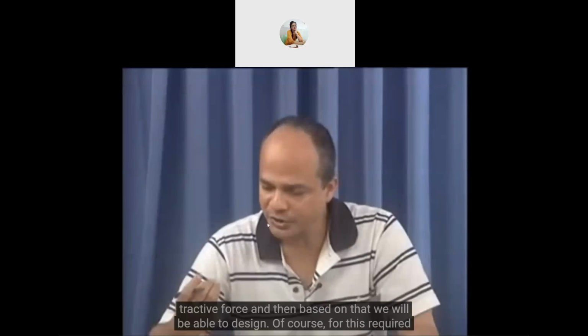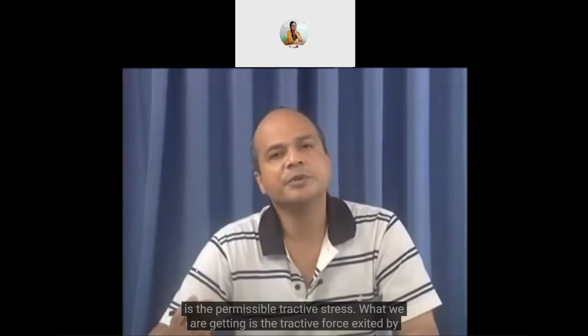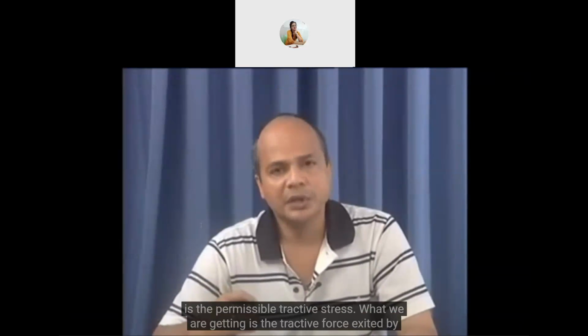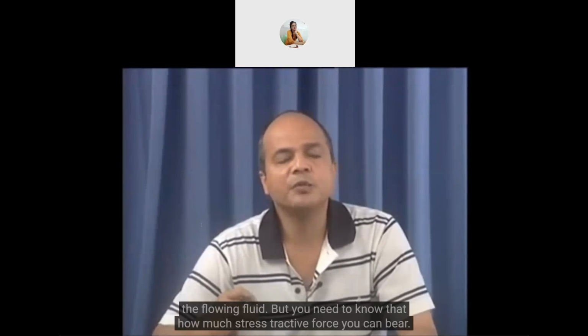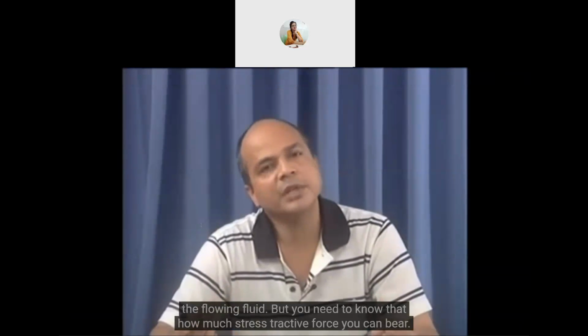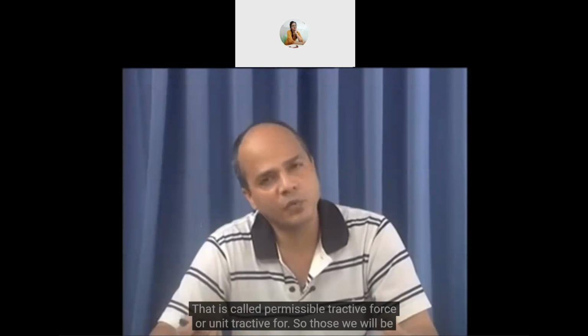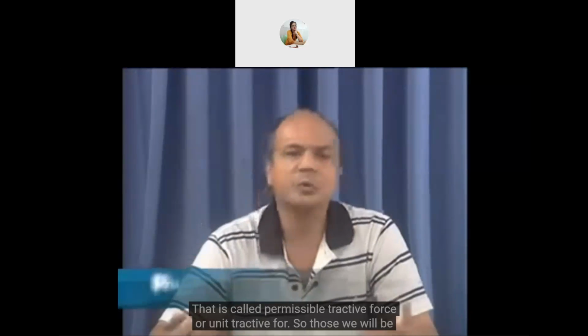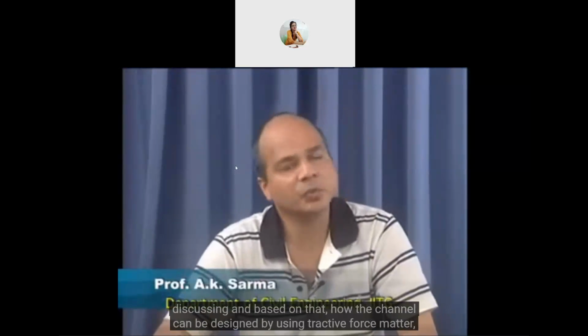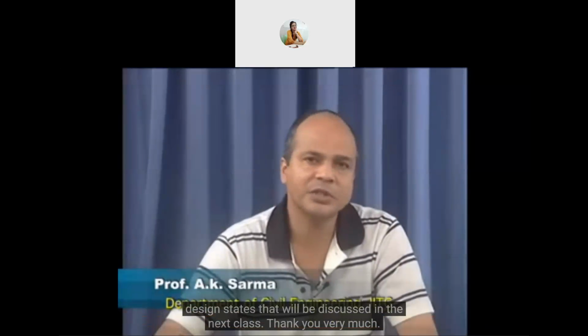Of course, what is required is the permissible tractive stress. What we are getting is the tractive force exerted by the flowing fluid, but we need to know how much tractive force the channel can bear. That is called permissible tractive force, or unit tractive force. Those we will be discussing, and based on that, how the channel can be designed using the tractive force method, the design steps, we will discuss in the next class.